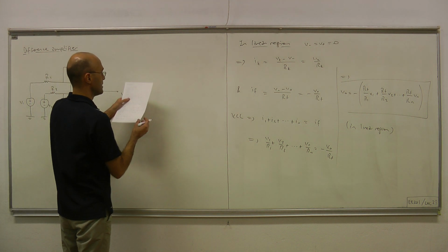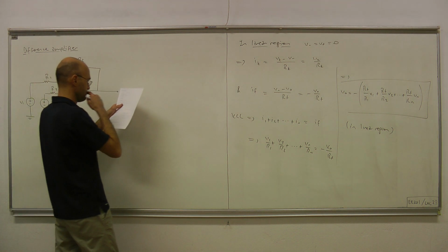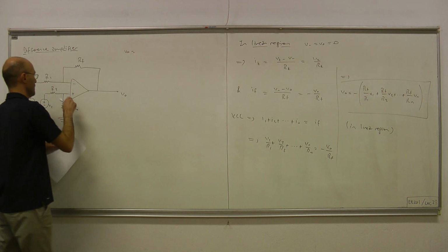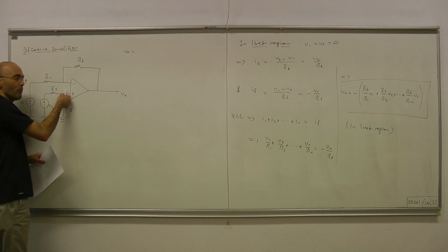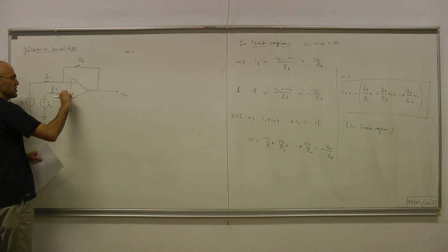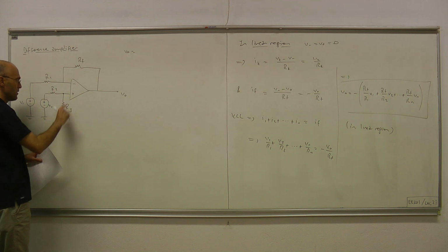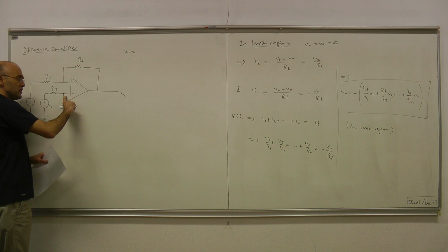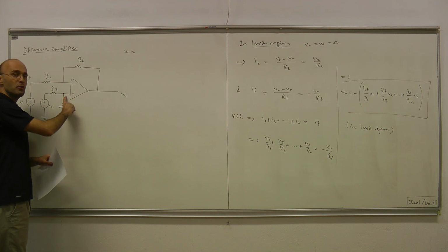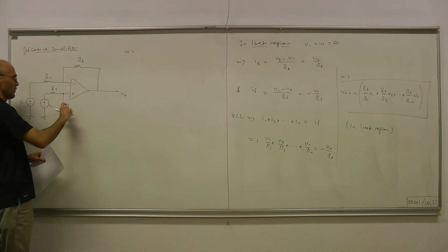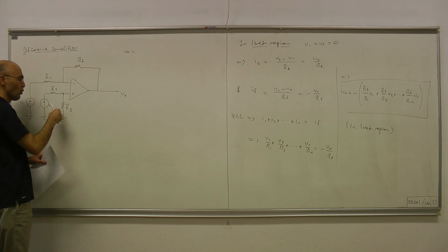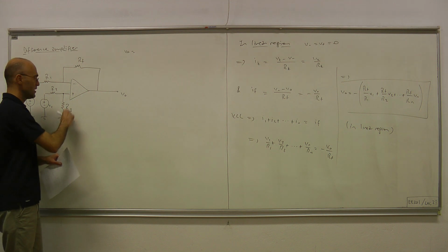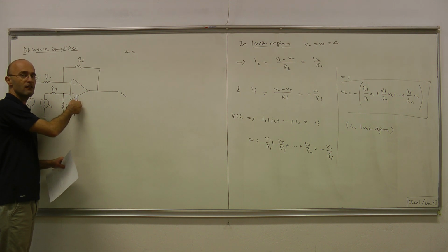Okay, so let's begin with V plus. There's no current escaping into the op-amp here, therefore we can just ignore this line when we're trying to figure out V plus. When you ignore that line, this voltage that appears here can be computed simply through a voltage division. R3 over the overall resistance seen by V2 must give us the voltage that appears here, which is no other than V plus.